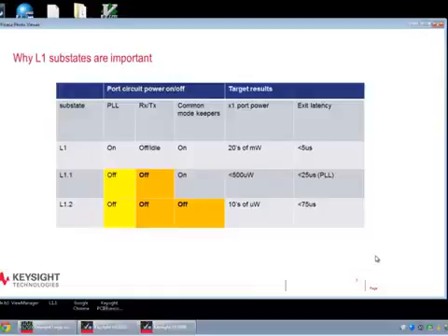The power savings are very significant. The typical power usage of a Gen 3 by 1 link is about 1 watt per lane. And that's across, if you're using a by 4 system, you're using about 4 watts. Well, the L1 state significantly reduces that to about 20 milliwatts of operation. But it has a very fast recovery time back to the data transfer state of about 4 microseconds,